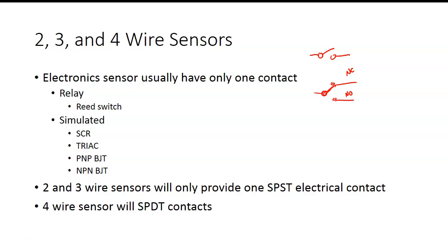Gotcha. Okay. So in motor controls, we would come up here and we would draw it like this. And then I'd come over here and draw another one like this. And then I'd put a dashed line between them, which means they're operated by one operator. This would be double pole. And then each switch has only got one position, so this would be a double pole, single throw. So the poles are the number of what? The number of switches that are controlled by the same operator.